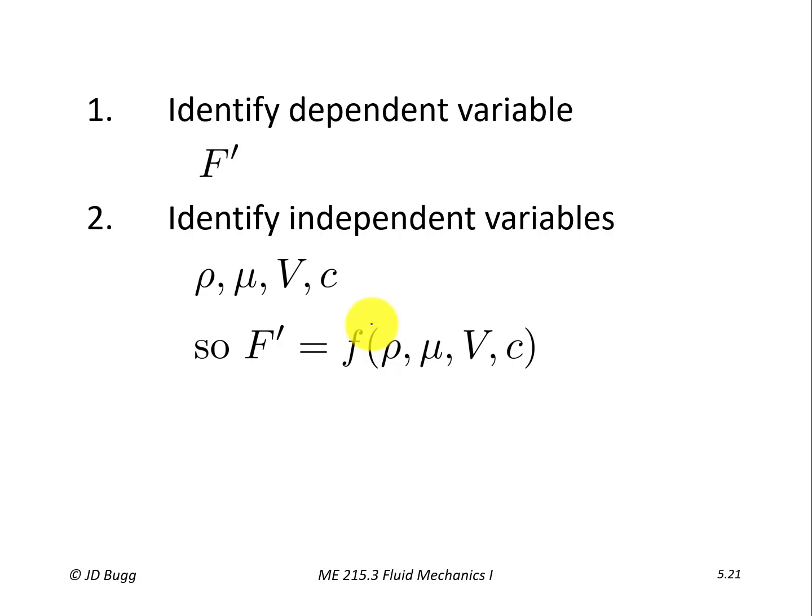But what Buckingham PI theorem will tell us is how can we rewrite this function so there aren't so many darn things changing on us. Here we've got 1, 2, 3, 4, 5 variables, combining our dependent and independent variables together. When we apply Buckingham PI theorem to this, it'll turn out there's only 2 parameters that are important, but they're dimensionless parameters. Okay, now continuing on with the Buckingham PI theorem.